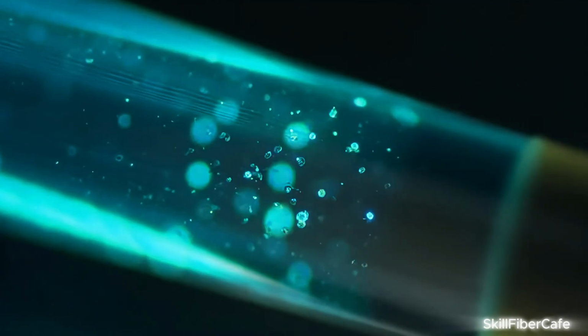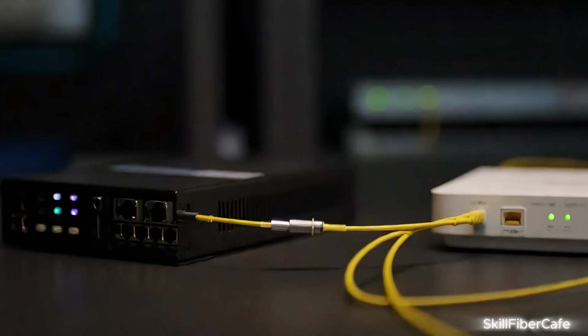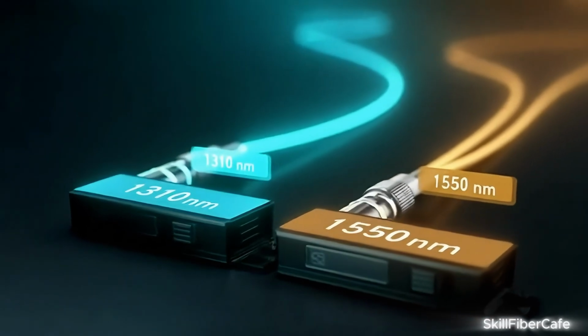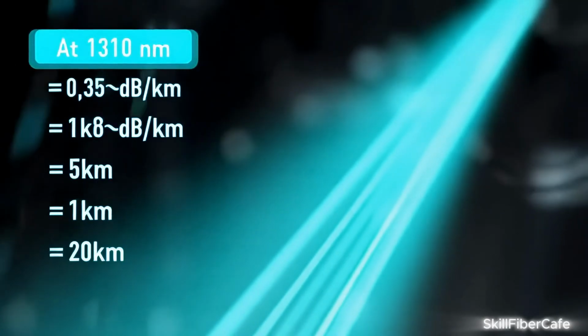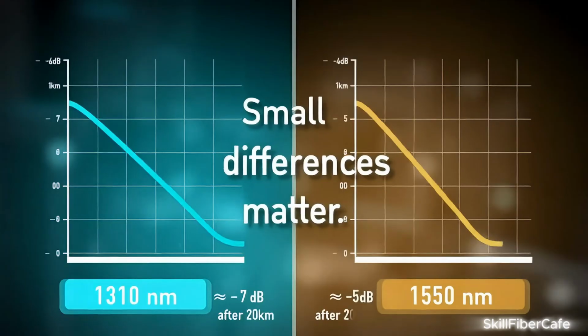Loss happens because light encounters imperfections: microscopic scattering, absorption in the glass, and small mismatches at splices and connectors. These tiny effects accumulate along the fiber, reducing total optical power. At 1,310 nanometers, single-mode fiber averages 0.35 decibels per kilometer. At 1,550 nanometers, it drops to 0.25 decibels per kilometer. These small differences become crucial over long runs.